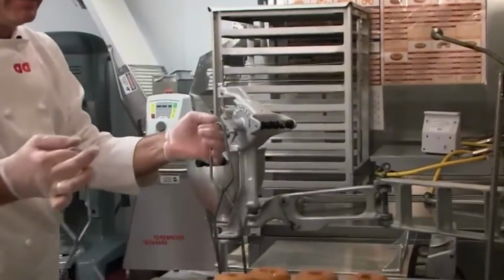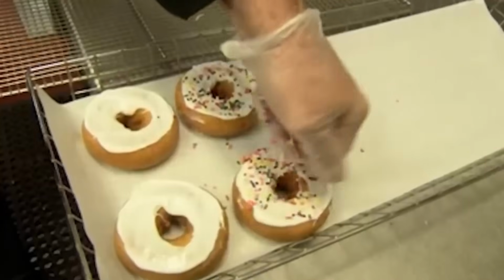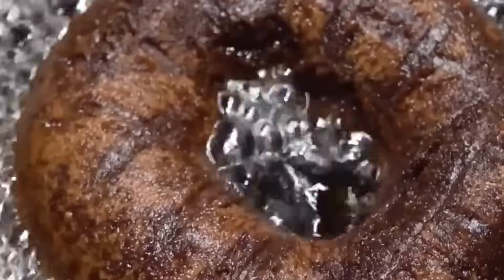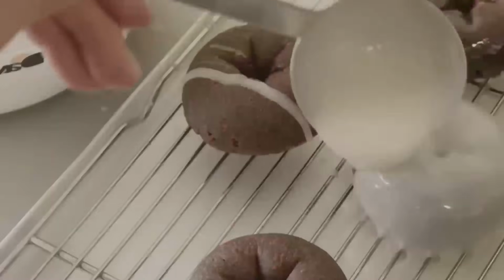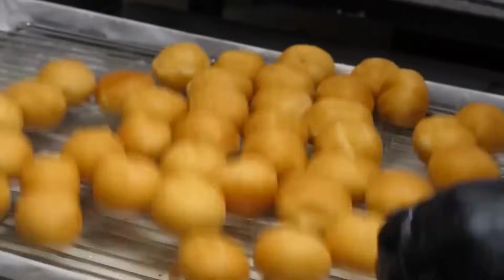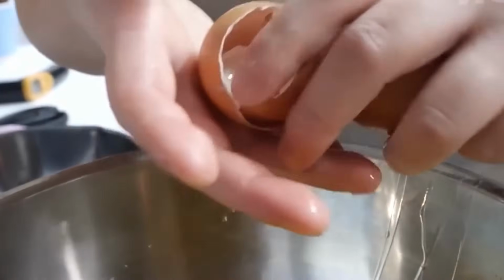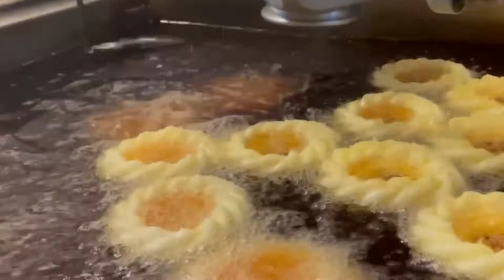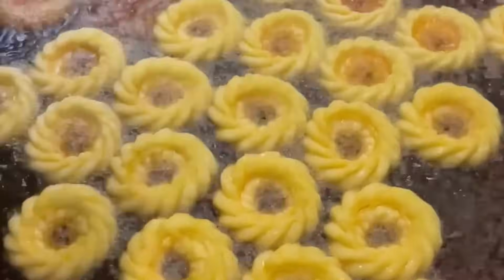Ring donuts destined for glazing pass under a waterfall-style glazing station. The glazing tank contains a high-shear mixer that maintains solution homogeneity. A recirculating pump delivers glaze to a curtain nozzle that flows over the donuts. Excess glaze drains back into the holding tank through a mesh screen.